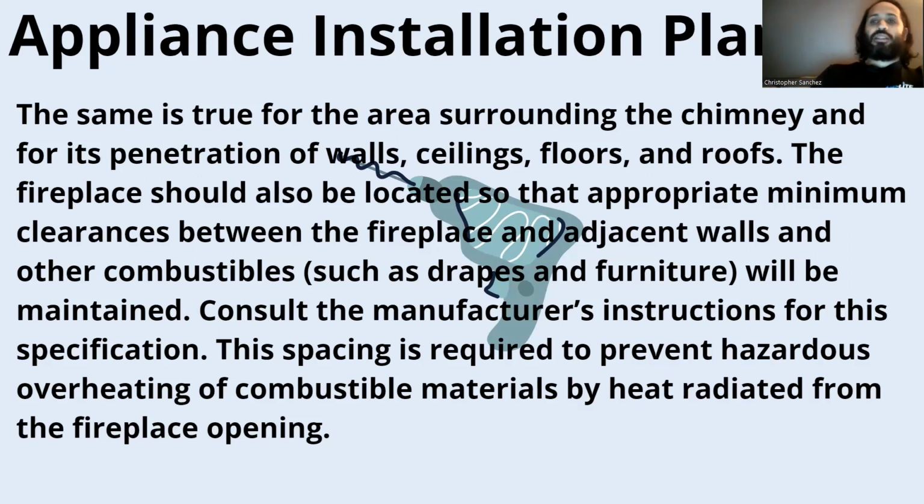Man, we always keep coming back to this, no matter what it is, but we're talking about the clearances to combustibles. It gets really, really boring, but it's super important to notate that no matter in what stage of planning we're in, we're seeing that those factors keep on coming into play. Like, how far is it from the adjacent wall? When you're doing corner installations, you'll see that it's not only about having the proper framing, but it's also about having the proper clearances from right to left, whatever walls are to the left and to the right of them. So, what furniture is going to go out in front of them, or an oil painting above.